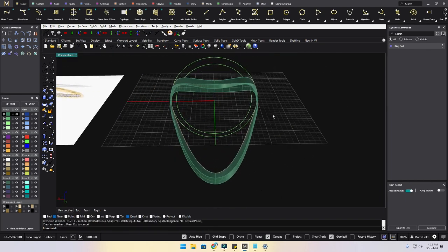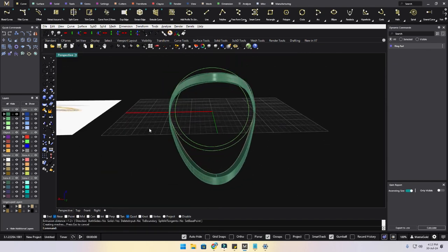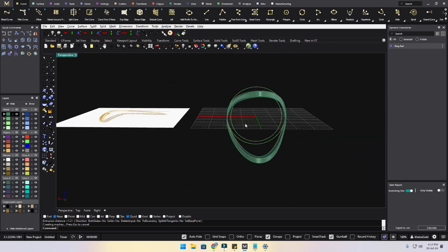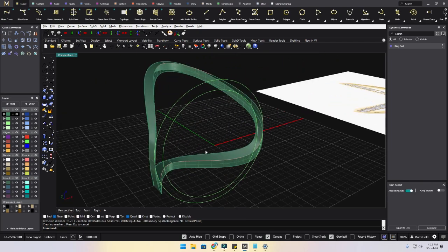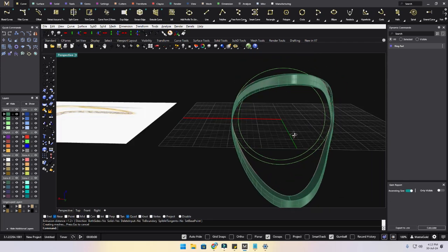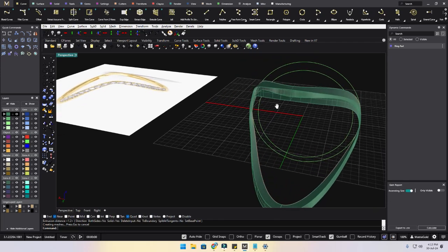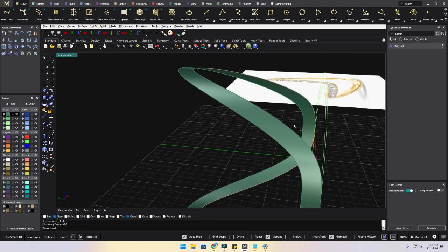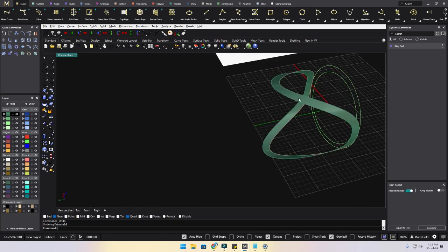Okay. So if you can see over here in 3D part, you can see how it has been shaped. For top, it is somewhat alright, but for the side ones, it is not proper. Okay, so that's the reason we do offset surface over here. So let me select again offset surface.